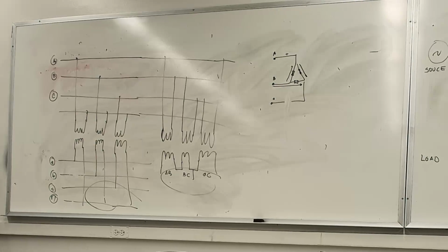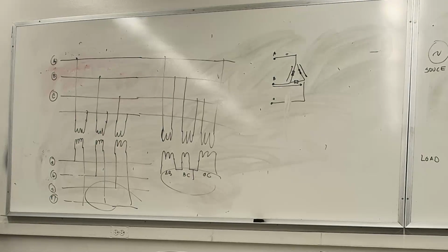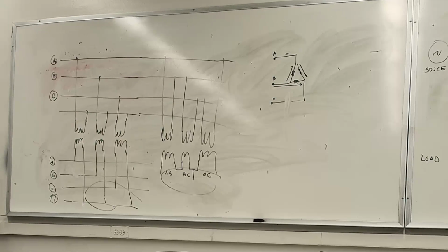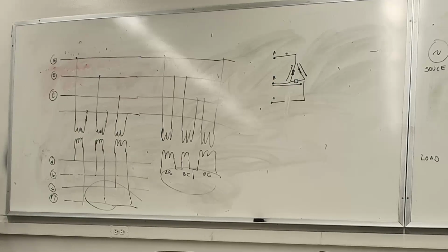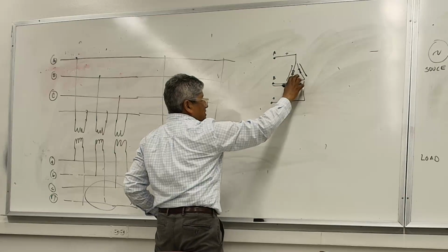I'm not saying that's exactly why LADWP, as an example, decided to have their distribution systems be delta. But I will probably make that argument, that to them reliability was really important, right? So if they lose one phase, they still can serve their customers, not permanently, but they can still run the loads while they fix the problem, and they never lose a group of customers, say on this leg right here.